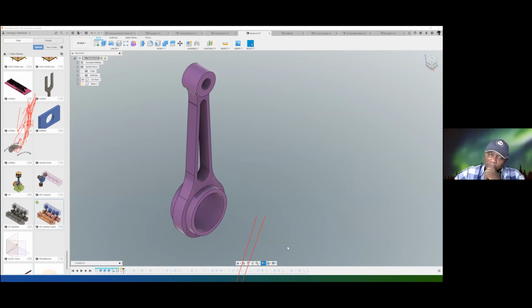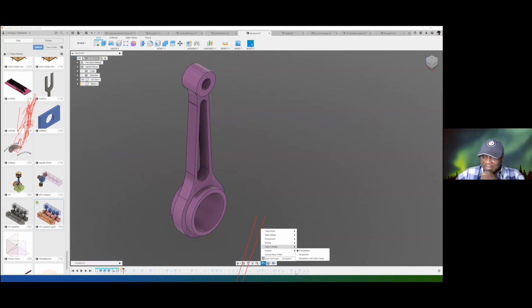You can also change object visibility. There are several things you can set here. The video will tell you about those I don't know all the meanings of; I only know the ones I look at. But one important thing you can set is the camera. You can set your camera between orthographic and perspective. In both cases, there is a vanishing point.